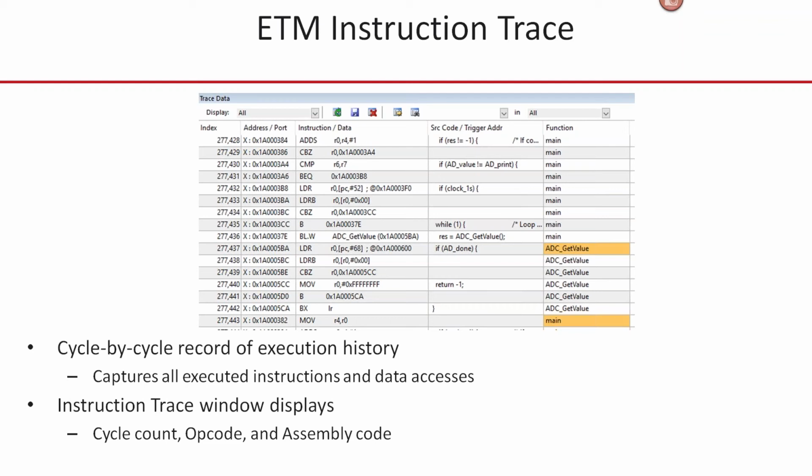So very often when you're trying to locate a specific problem, it's being able to control the trace and filter in information rather than recording everything. Otherwise you just end up with reams and reams of information and the problem is buried in there somewhere. You need to be able to shrink the trace down and get directly at the problem that you're trying to isolate.